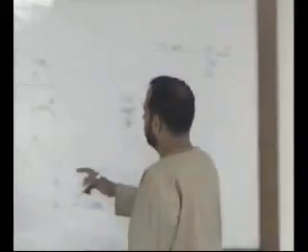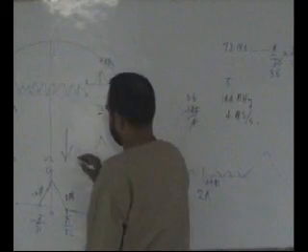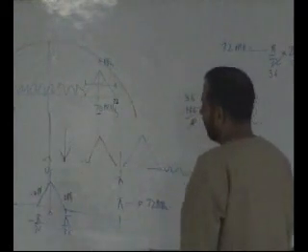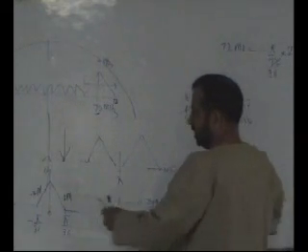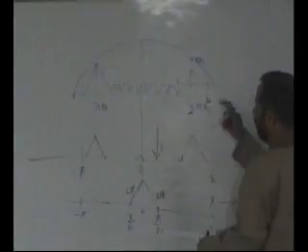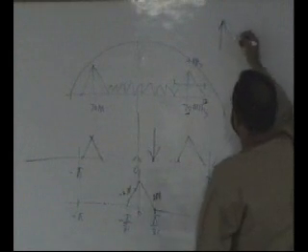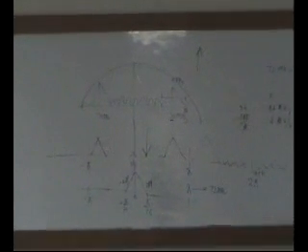In this case where you are moving the spectrum down, you always downsample it. It is shown with this arrowhead. And whenever you move it up, because in the transmitter you need to take the spectrum and move it up, you always first need to move the number of samples up, and then you have to mix it with an exponential.